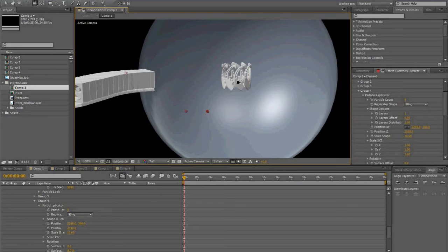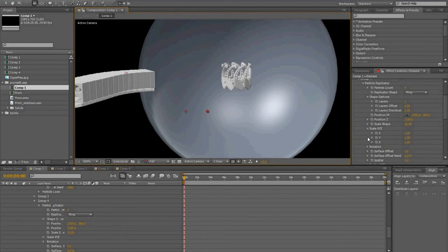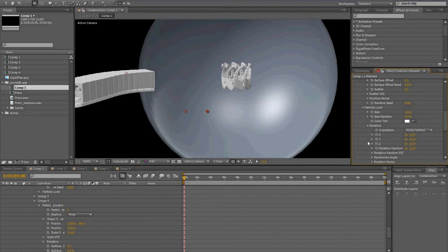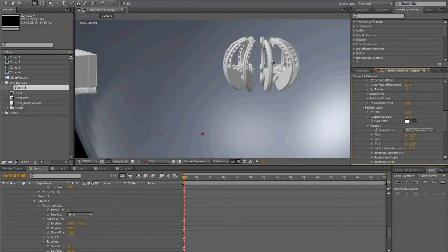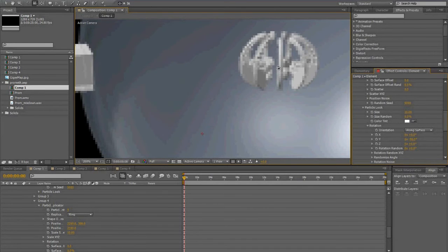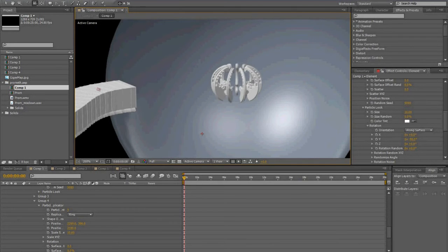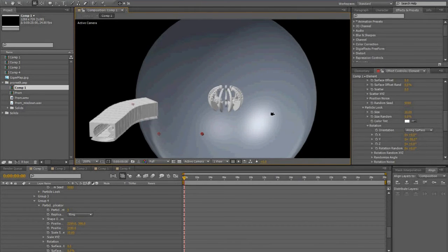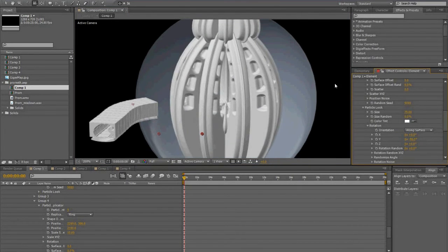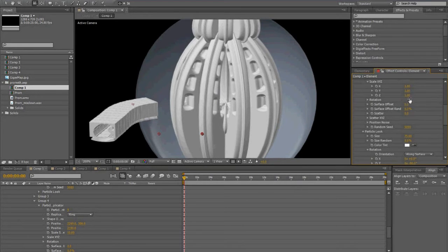And then if you go into the particle look and the rotation, if you rotate along the y-axis, what that's going to do is bring all of the points inward and create this sort of spherical outer edge now. The outer edge is now going to the outside and will match up perfectly with the sphere. So now I just have to adjust the scale of the particle. I used 75 for the sphere, so if I use 75 for this, it normalizes the shape. So all shapes are basically the same size in Element.